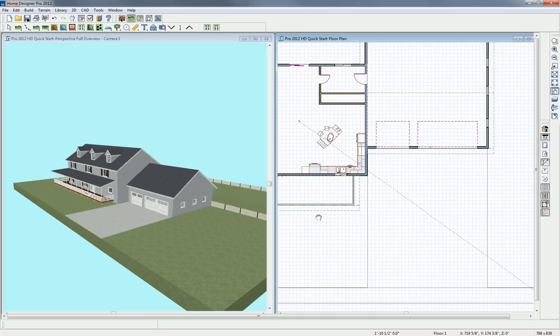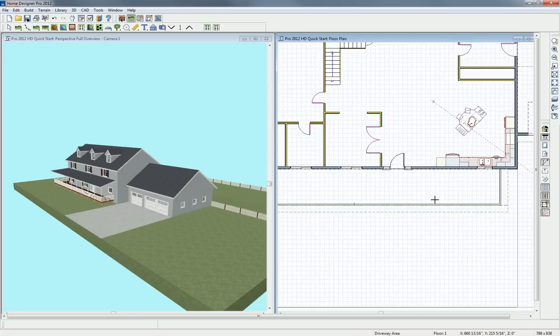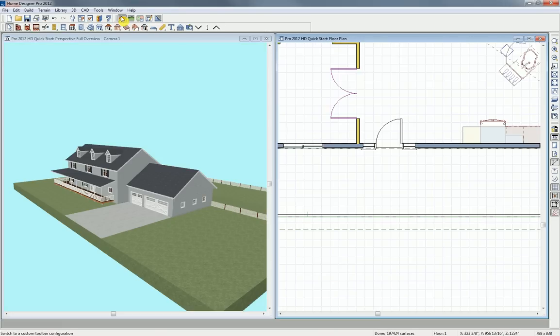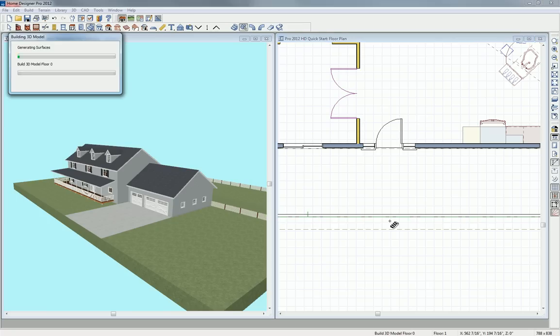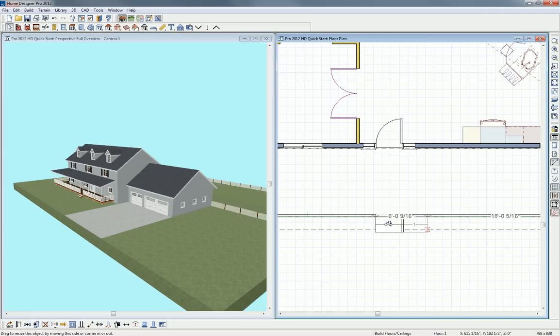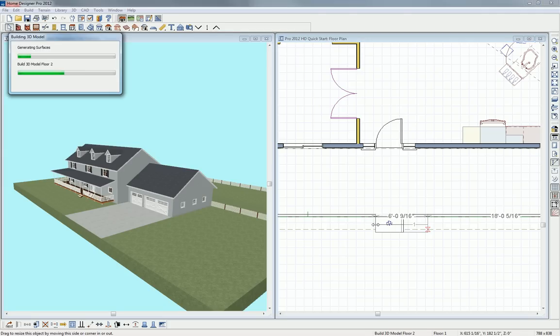Now let's go ahead and add some stairs going on to the front of our porch. I'll go back to our standard configuration, and under our stair tools, select Click Stairs. I'll place my cursor right outside of our deck railing and click once. The stairs will auto-generate and reach my terrain. I can just increase the width if I'd like to.